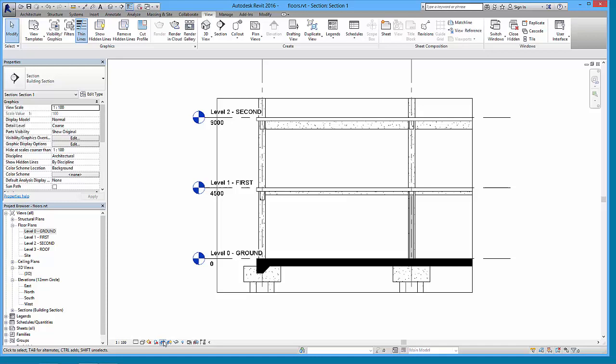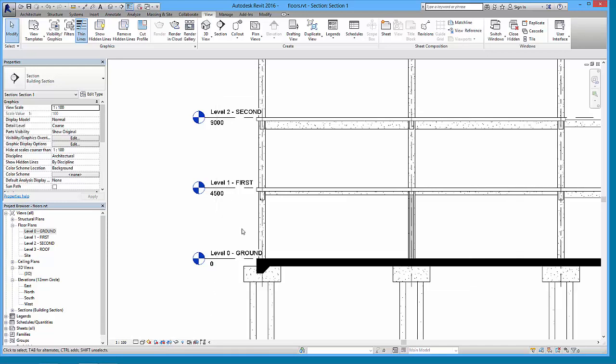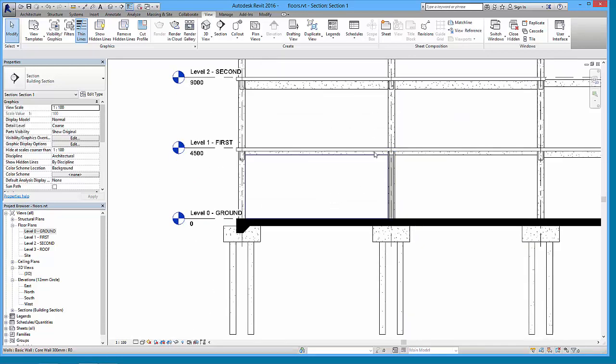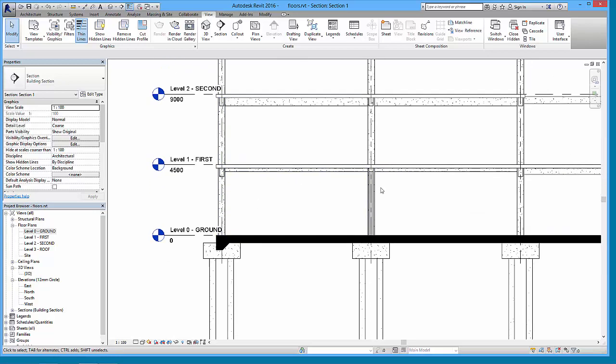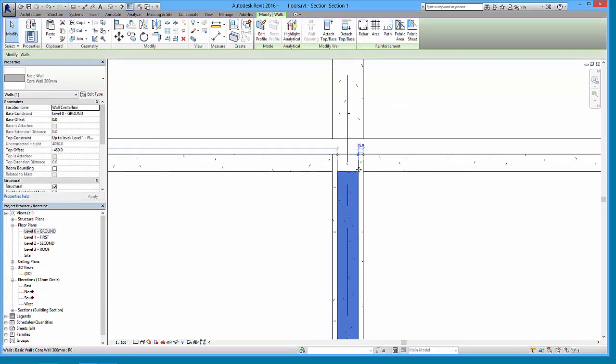We've got all our crops turned on and active, so I'll just turn that off, and we can see that our walls have come in to this point, and I think that they should be down at this level, because I think these beams are the same thing. So whilst it looks like it's right, it's just that they're being obscured. But I want to select this and just set this value down to maybe minus 800 at the moment, just so we can see whether it will apply that. There we go. There we can see it now as the distance between top and bottom.